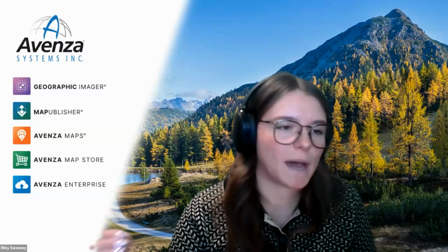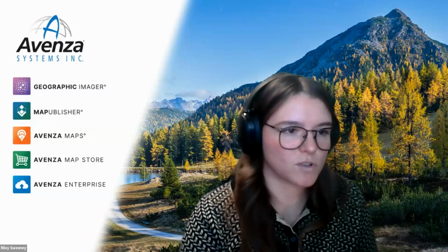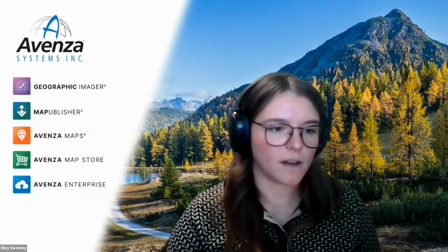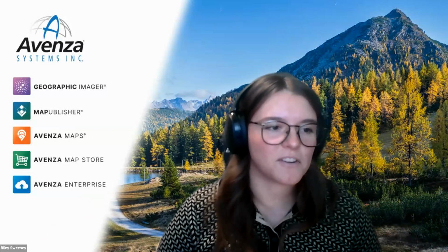Yeah, I think that's something a lot of people don't consider. You can definitely create your spatial data in Illustrator. There are tons of drawing tools, different shapes, or even just manually drawing that you can utilize. You just have to make sure that you're drawing into a map layer. If you go to your Map Views panel and create a map layer from scratch, you can have that as your active layer and draw right into it, and it will inherit all the geospatial information from that map view. So I think a lot of people miss out on that. They don't consider that you can create your data, and you absolutely can.